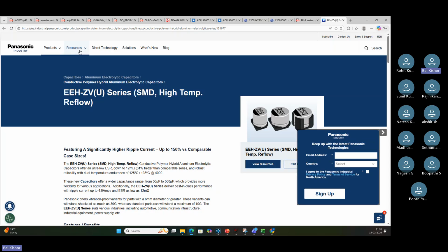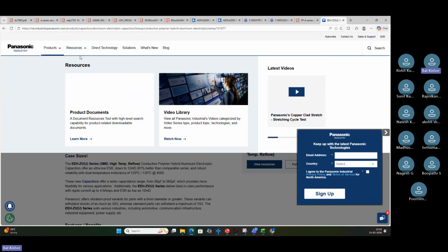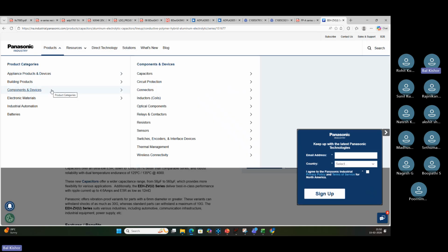These days, this tantalum capacitor has one more disadvantage: they break. Like if you put your hand or something firmly, they will break. So they have come up with the polymer capacitor, which is a little costly but better. They have better mechanical strength compared to tantalum, and they have higher accuracy also. Like they do not change.